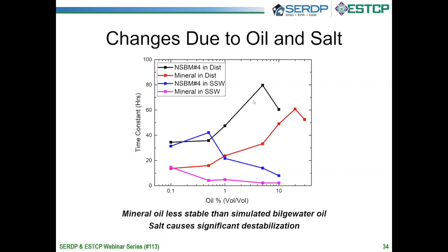That these large droplets, yes, ordinarily, if unhindered, will come out at a certain rate. If they have to travel centimeters and they've got 10,000 slower moving droplets ahead of them, they have to get around them. And if there's some sort of colloidal scale attractive interaction, then all the more they'll be dragged down and slowed down. So there seems to be an increase of hindrance to a critical point. But then after that, it seems to destabilize again.